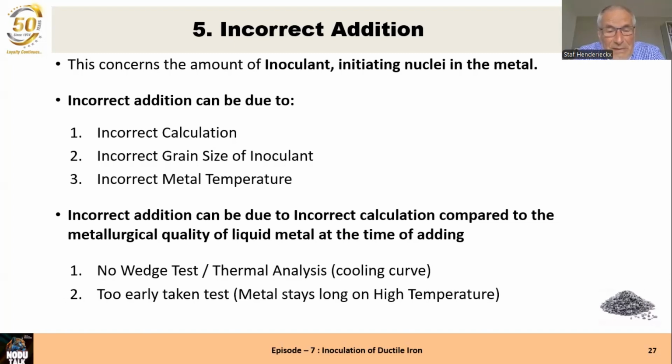If we have no wedge test and no thermal analysis, I doubt that you ever can do the optimum inoculation. Sorry to do it like this or to tell it like this. I doubt if you have no wedge test, no thermal analysis, you don't know how much inoculant your metal needs.